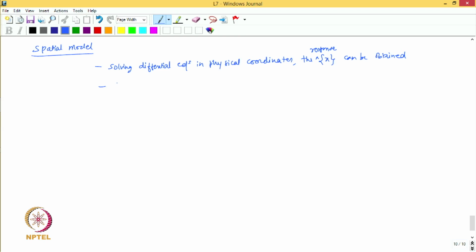And these equations require the knowledge of the mass and stiffness matrix to perform an undamped analysis, right, to solve the response based on the undamped model. So, knowledge of mass and stiffness matrix is required. If this is available, then we can find the response to the given excitation force, and that is why the mass and stiffness matrix together is referred to as a model of the system. They make up a model of the system, and this model is called the spatial model, right.